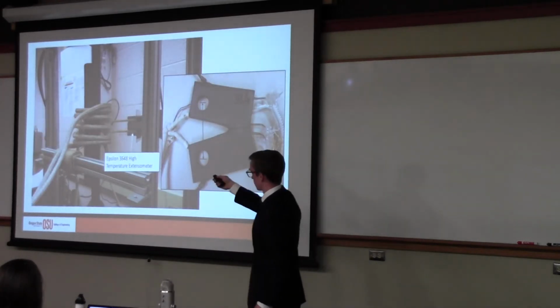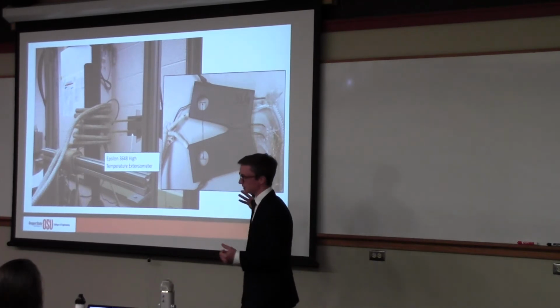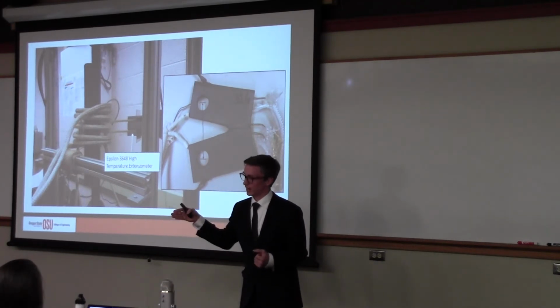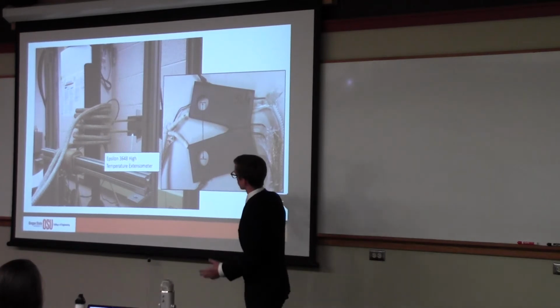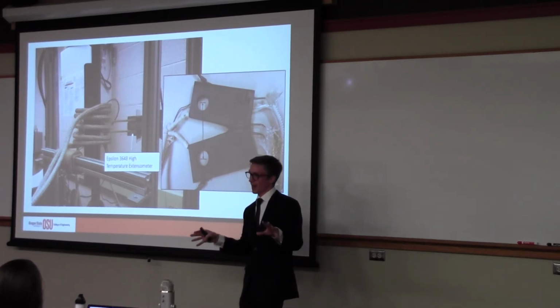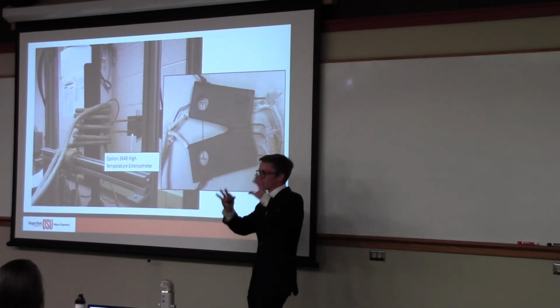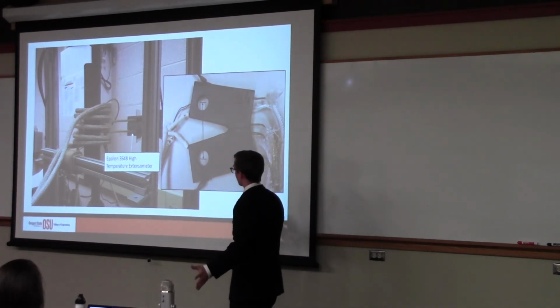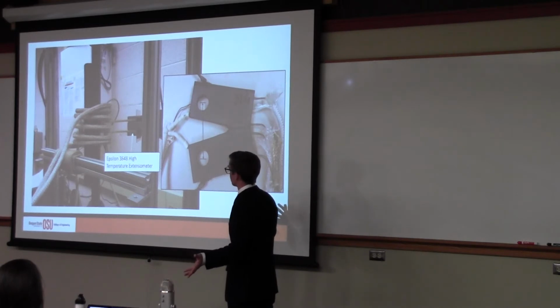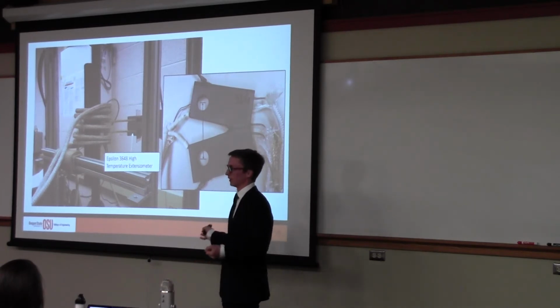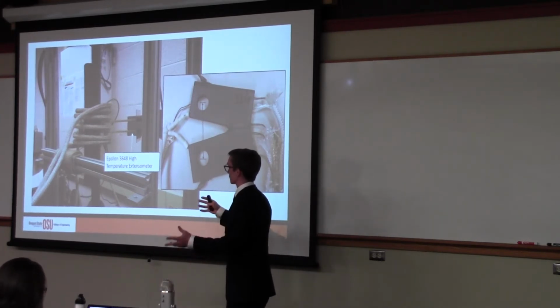This is, like I said, another coil, and it's modified so that we could stick a high temperature extensometer into it and measure something that's very important for the whole time-dependent aspect of this problem. If you don't measure this, then you're missing this whole aspect that otherwise you can sweep under the rug by just gathering the K data, the stress intensity data.